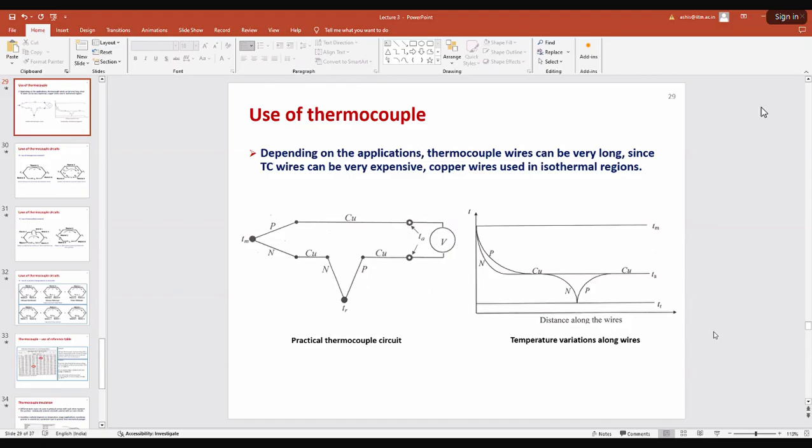Got it, sir. So if I'm trying to correlate it correctly, in the example I was quoting, Tm would be the surface temperature that I'm trying to measure. Yes, Tm would be the pin and the surface temperature. Your TR, I don't know whether he would have used ice or simply hung it in the ambient. It was simply hanging in the ambient. If it's simply hanging, the problem is that, when the ambient condition is well controlled, let's say you have a controlled lab environment, that means the temperature is not changing so much, right?